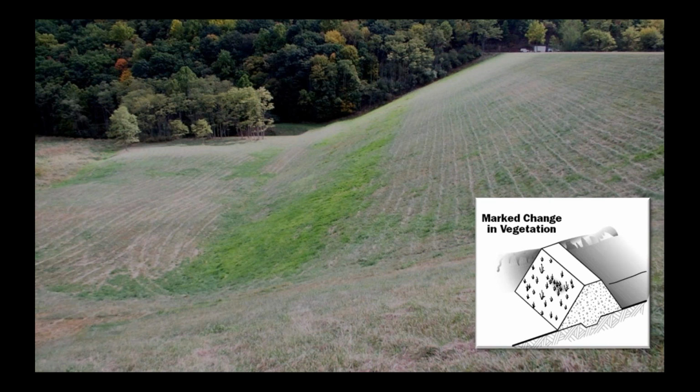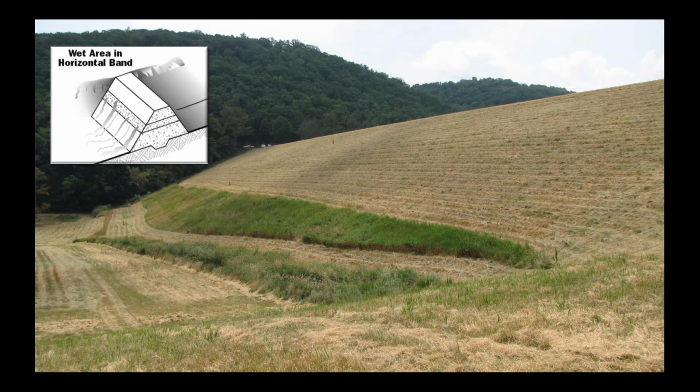Another thing to look at when you're inspecting the dam is look for differences in the vegetation. Here it's clear that something is going on. We have a lot greener vegetation right in this zone. And here's another picture. In this case, the person that was mowing the downstream slope, when they got to this zone, they mowed around it because it was so wet and soggy that it was hazardous to mow. So essentially what they did is they mapped out the seepage zone within this particular embankment.